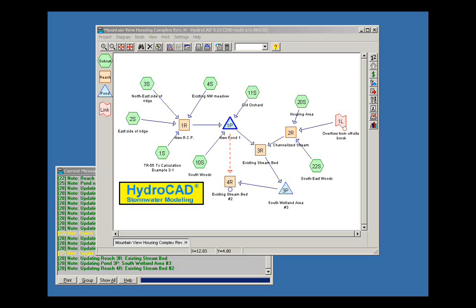One was that he had the soils areas delineated, but not all the line work was on that correct layer. So he said, well, the areas are defined, but the software only looks at the geometry on that one layer, so all the line work had to be there. And then we discovered a ground cover polyline that looked closed but wasn't. And once we solved those two issues, it just worked like a charm. So okay, good. I'd love to have everybody give this a try. What else? Are we missing anything else?